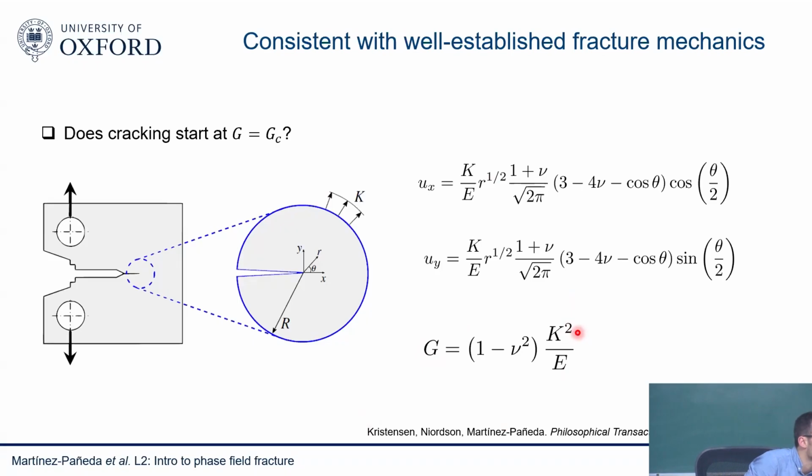When you keep on increasing, the K field is not applicable on some sides. That's correct. So what we discussed before, if you have, here I'm just looking at linear elasticity, so it will always be applicable. If you have an elastoplastic material, you could have some edge effects, I guess, depending on the size of the sample. If you have an elastoplastic material, eventually the plastic zone will be so large that your K field will become invalid. What about the first terms of the infinite series of Westergaard's? Yes, so you have a T stress and other things as well. You could actually add them if you wish to. You could have a constraint effect, for example, with a T stress and so on. But in principle, this is the dominant term of the Westergaard series.